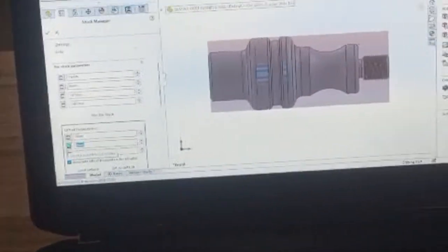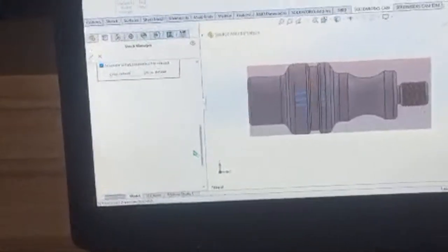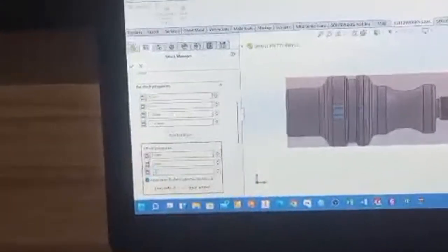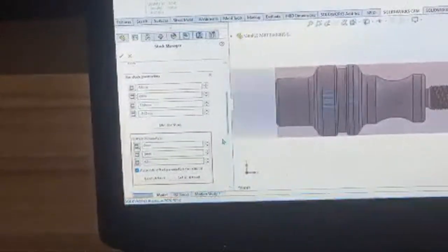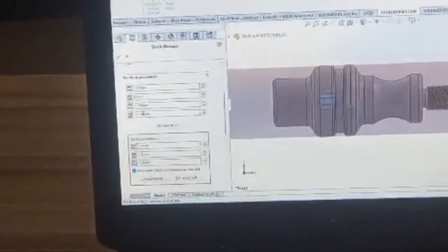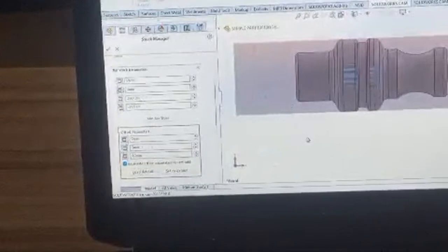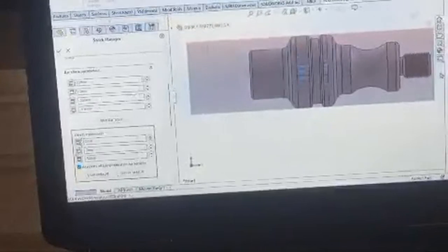Let's say I'm going to do facing. So if the material is extra by 3 millimeter, I'm going to add 3 millimeter. Then it will update that one. Then here where I'm going to clamp, so meaning I can add like 50 mm. So this is the place I'm going to offset to clamp my workpiece. And when you place here, the value also updates here on the base stock. This section, you see it has added because it is where I'm going to clamp to hold. And then this section is also affected by 2 millimeter, where I'm going to do facing.